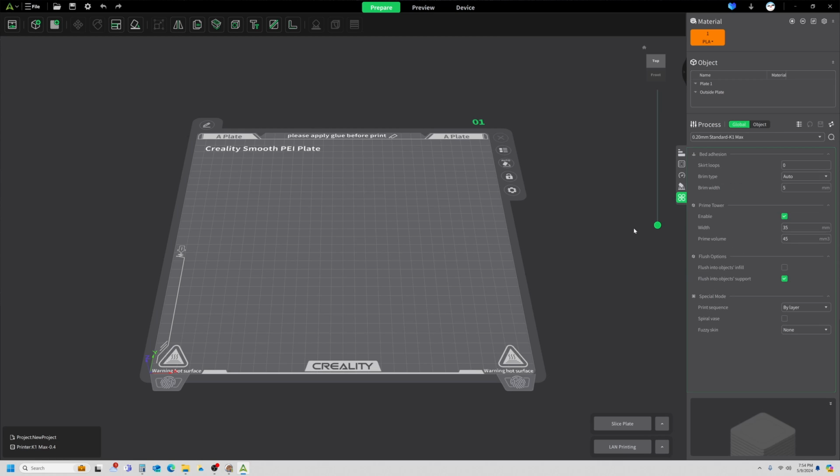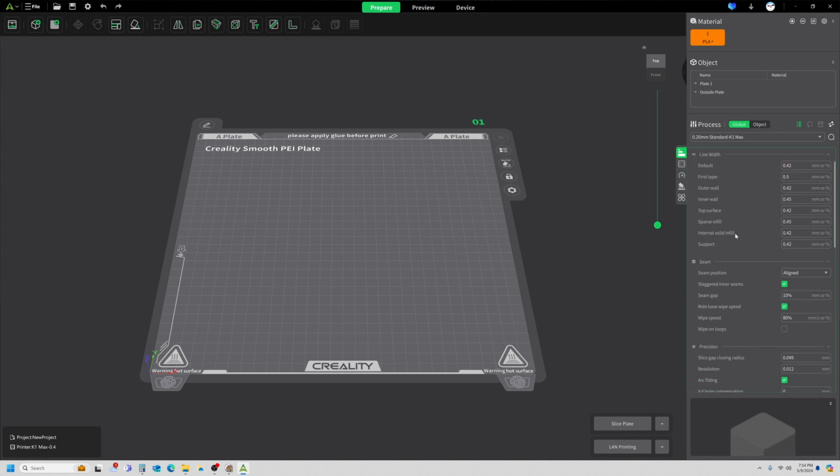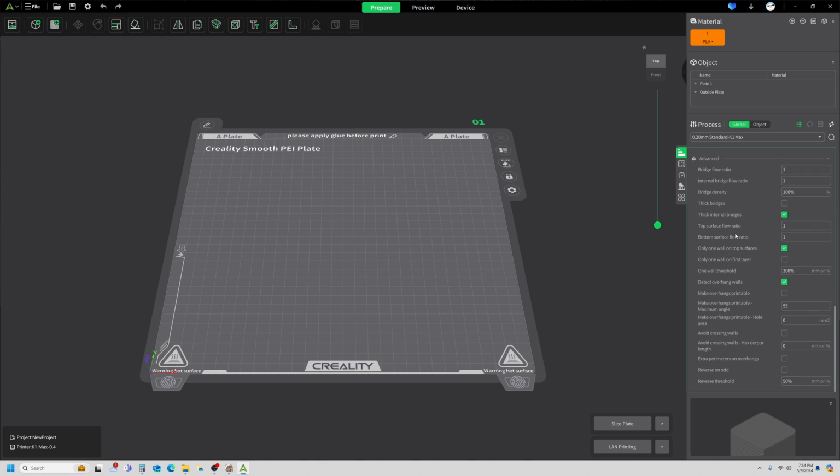And other, for anything that just fell into different categories. We'll talk about the other in just a few minutes, but let's go back through real quick. Going back to quality, if you really want to control your slicer settings, to the right of the word object, just click this icon. It looks like 3 slider bars. Go ahead and give that a click, and bam, you have access to more than you could ever hope for to change your slicer settings.